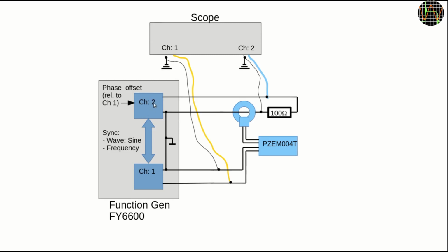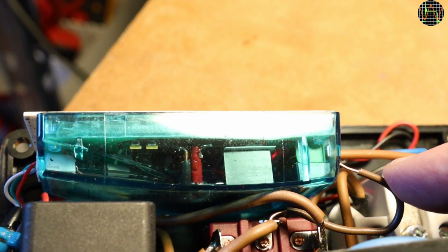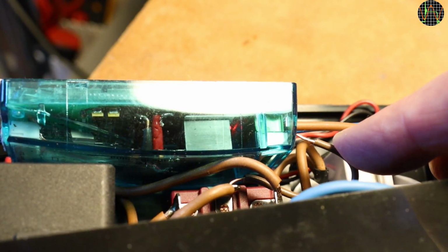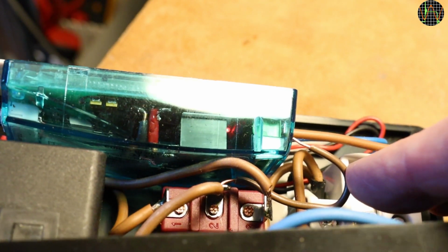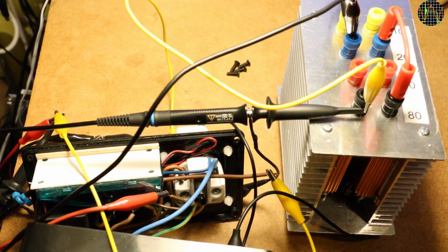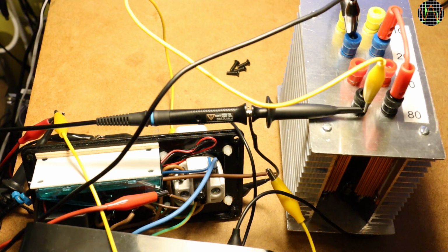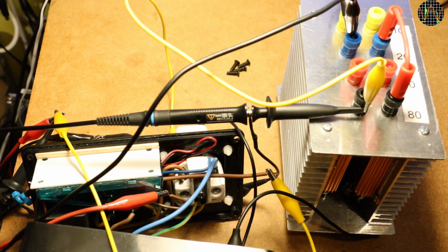While using only function generator voltages and current for this test is good for safety, the values are borderline of what the PZEM-004T needs to get accurate measurements. The modification to allow voltage and current to be provided separately is easy. Just remove this wire from the terminal and add a temporary wire to allow direct connection to the function generator channel 1 output. Since the whole test uses only harmless voltages and currents from the function generator, all that flying wiring is okay in this case. The power resistors are definitely oversized for this test, but I love using them because they are very convenient.